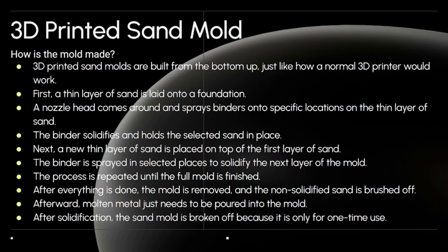The unique thing for 3D sand casting is that the 3D printer will not make the structure itself, but rather the negative of it, which means that it actually makes the cover or the shell of what the structure should look like. So the inside is hollow and it is the shape of the structure that we want. It is way more precise and you can add a lot of fine details to it. This saves us a lot of time, effort, and money.